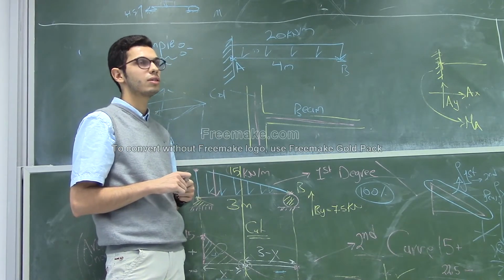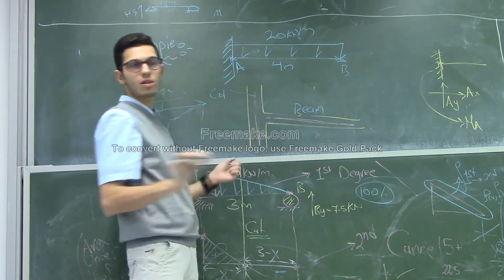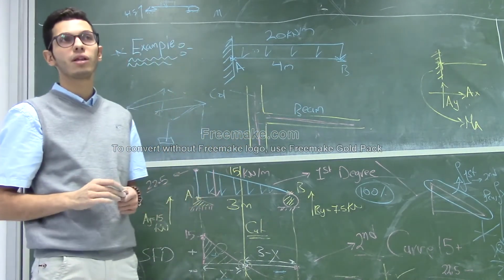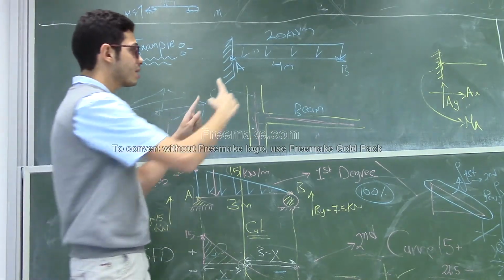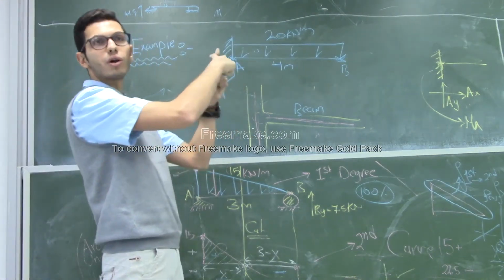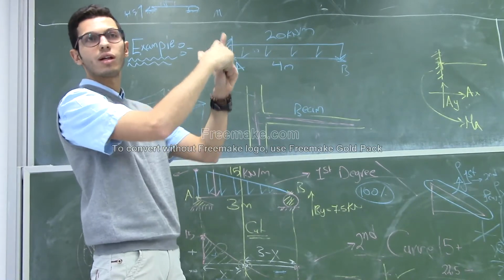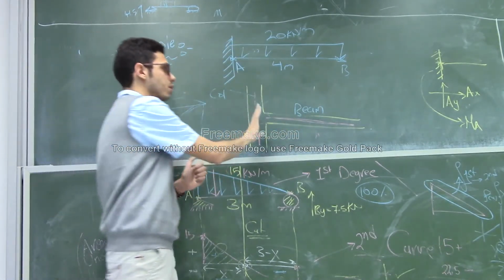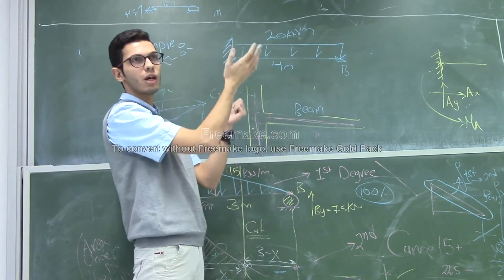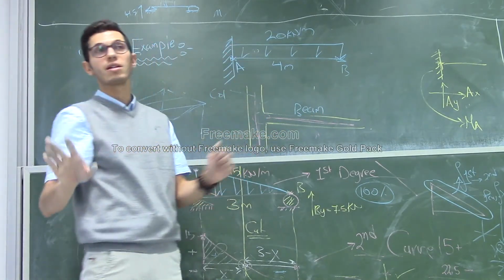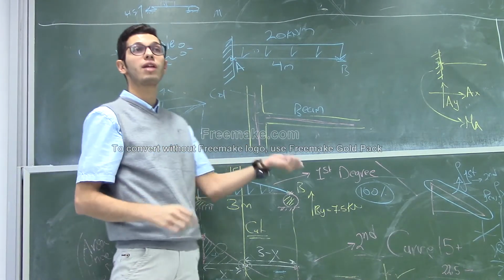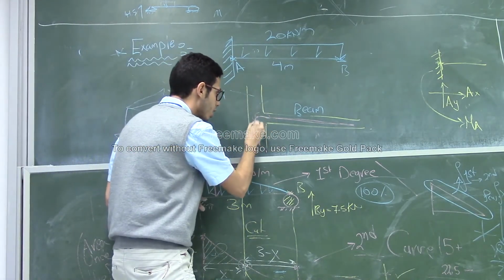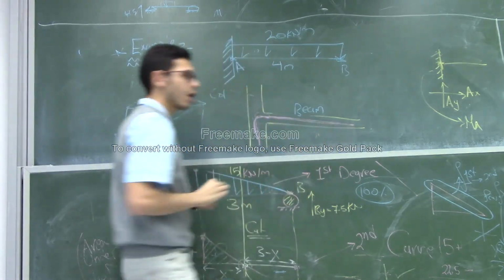There's still concrete, and the concrete connection is okay. But now there is no steel connection, so it's a pin. If the steel of the beam and the column does not cross each other, each of them is independent of the other. This case is the pin case. But if you need a fixed case, you should make a connection between them.